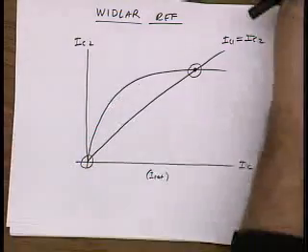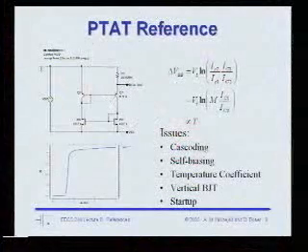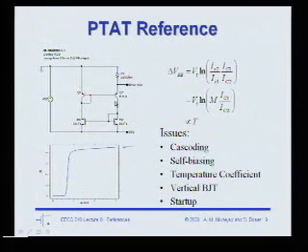And how do we do that? Well, that's pretty simple. If we go back to the slides, we can see that a simple current mirror forces the equality in currents, and that gives us the operating point where this circuit will generate its current. And now this is more or less independent of the supply voltage.